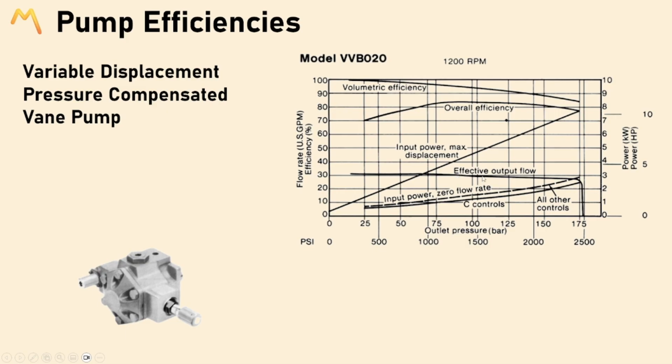Coming over here to the right and increasing our pressure to, let's say, 175 bar, we notice that we start getting a steep decline in the flow rate, right? Tracing that horizontally over here, our volumetric flow rate in gallons per minute drops to about 25 gallons per minute, and then sharply drops off after there from about 75 bar to 180 bars maybe. Yeah, somewhere in that range, where we get a sharp drop off in flow rate.